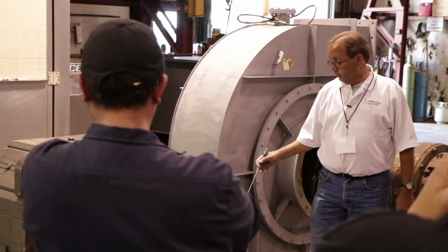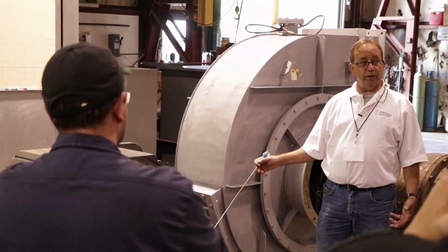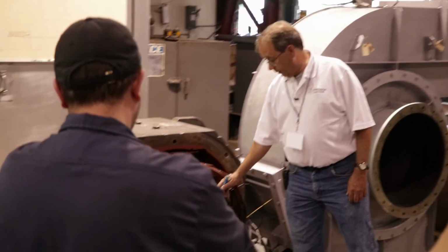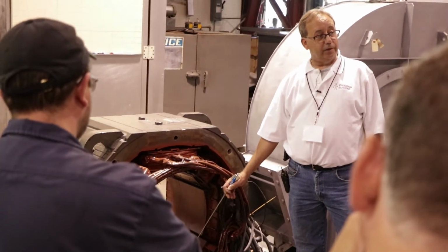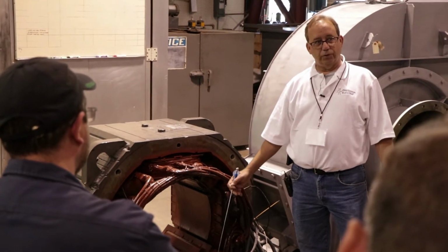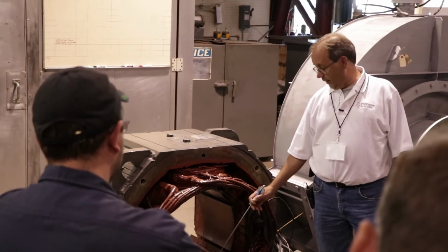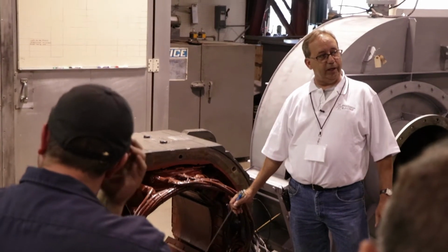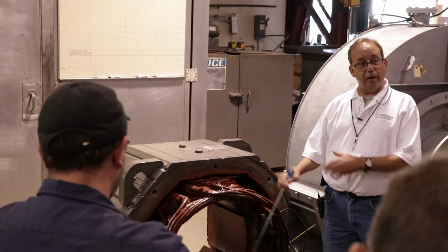So if you've got, say, 200 turns at 2 amps, that'd be 400 amp turns in your shunt field. You might only have one turn in a series field, with 400 amps. You still have 400 amp turns. So you could conceivably cancel out your shunt field completely if it's hooked in the opposite polarity of the shunt field.